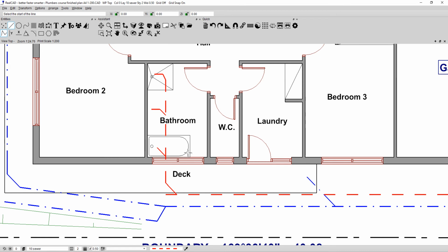And then we've got our WC, so I'll pop my line in here for the WC, comes through the wall, out to there, hold down the Control key and the Shift key, come to this line and click. You can see I've overextended. We can use the trim. I'll come back and trim that. Oh no, I'll trim now. It's debatable as to whether it's better to do things now or later. In fact, I will do it later.